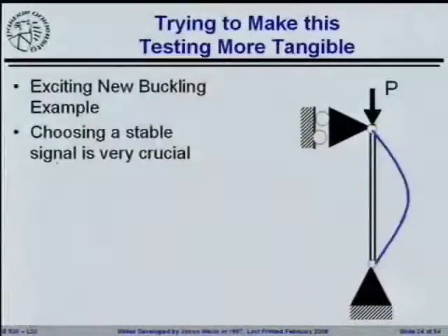Does the displacement change then once you start to reach the critical value? Or do you continually go at the same increment all the way through the test? You could change it if you want. Normally is sort of an odd word. Many times people go at a constant rate just because it's easier. But for example, in some of the tests that they're doing in the lab, when they do a test like this we'll do the exact same thing but controlling crack opening.